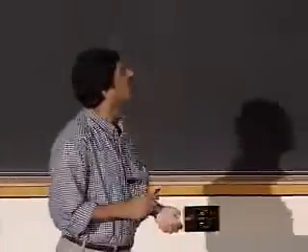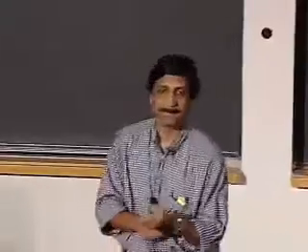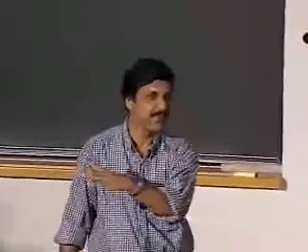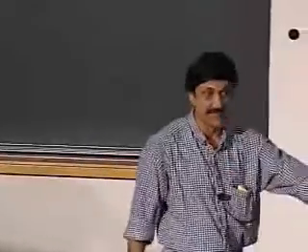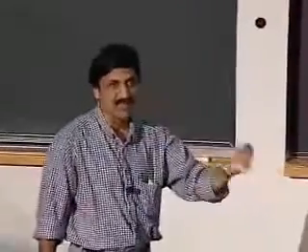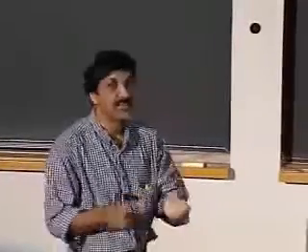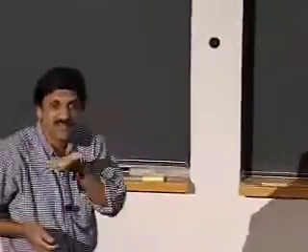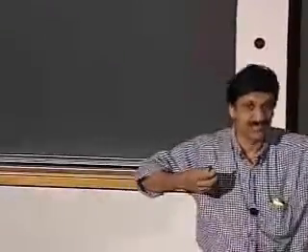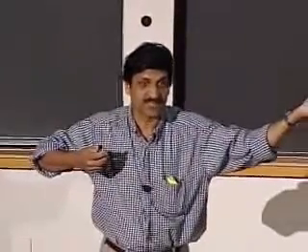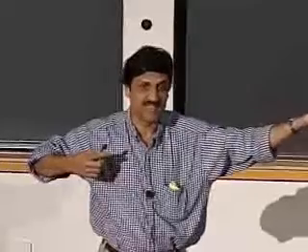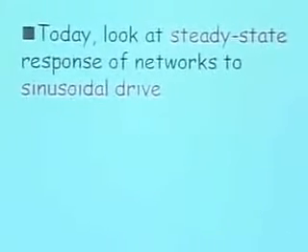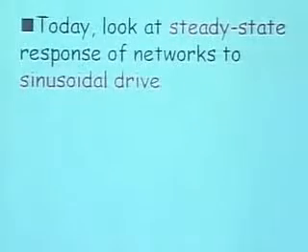And second, I'm going to look today at sinusoidal drive. Those are two things that are different from what I covered in the past. In the past, I looked at the transient response, and then steady state. And remember, for a DC input, for a DC voltage, the steady state was a DC voltage across the capacitor, correct? So the steady state was pretty boring. But what we're going to do today is, instead of having DC inputs or step inputs, which settle to a DC value after some time, we're going to drive a circuit with a sinusoidal input.